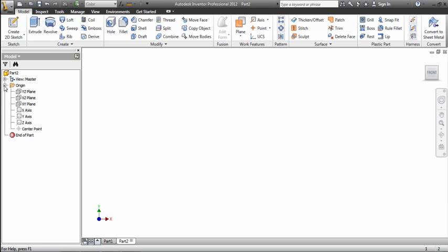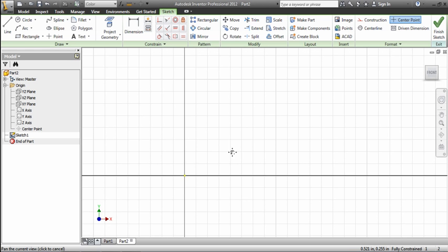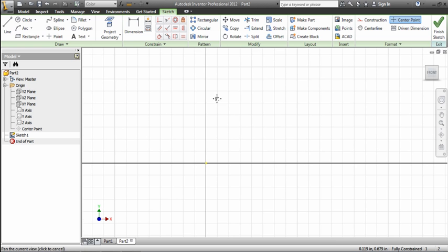First, let's go to the origin, and I'm going to choose the XY plane, or the front surface. So I have my front facing me, XY plane. I'm going to create a sketch. Now, what we're going to do is I'm going to actually draw a line that I'm going to revolve around, but you can also revolve around any of the axes as well. So I'm going to draw a line, and I'm just going to draw on the right side of my y-axis here.